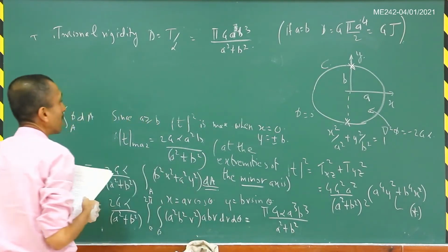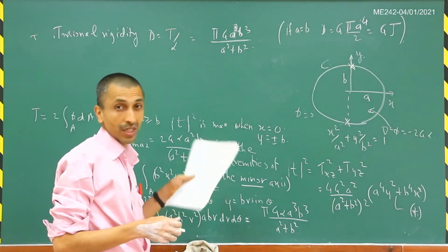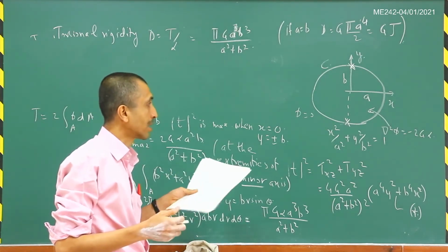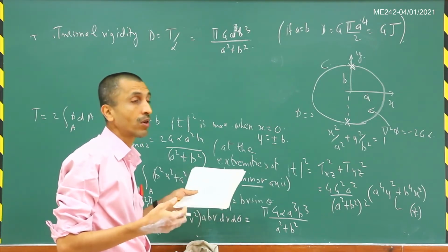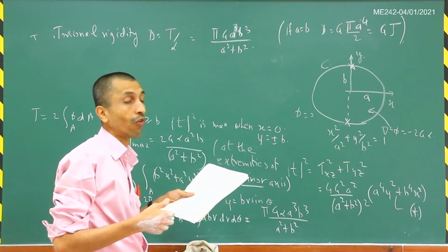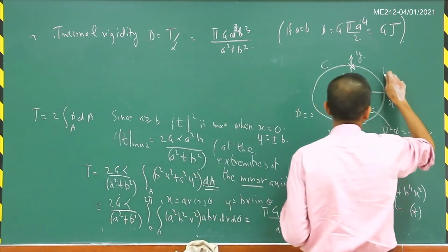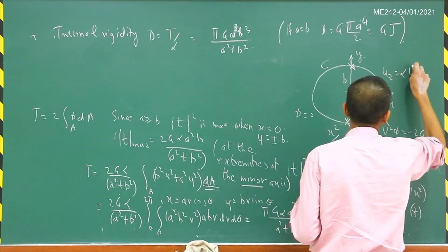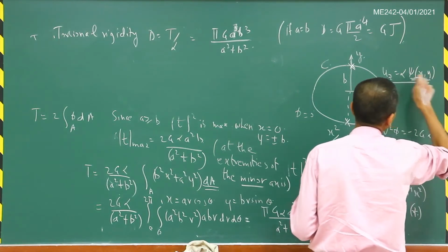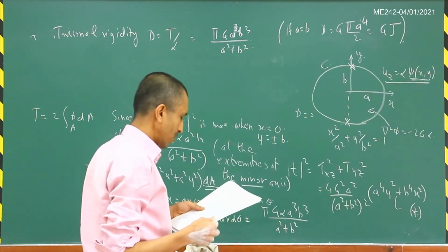So you can see that now we are able to find the entire stress distribution by using this Prandtl stress function. But in order to find the displacements, we still need to find the warping function, because we have seen that u_z is equal to alpha times psi of x comma y. So we need this warping function in order to find this component u_z.